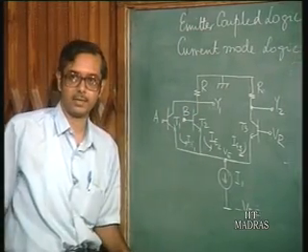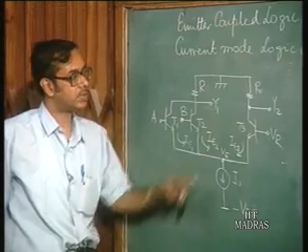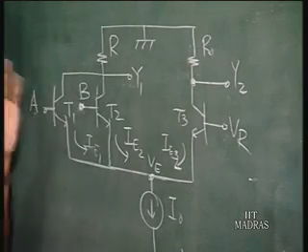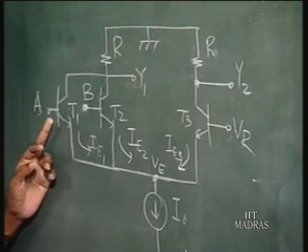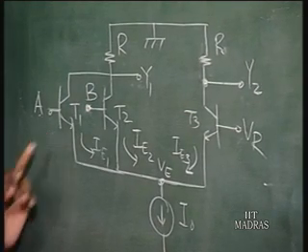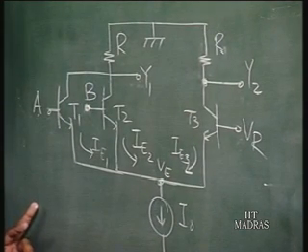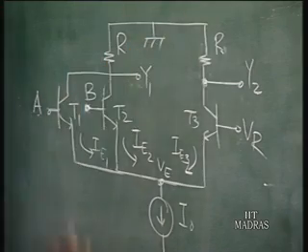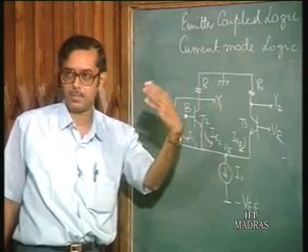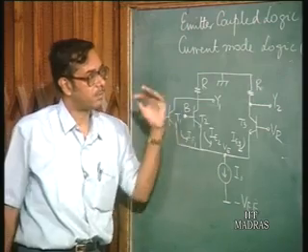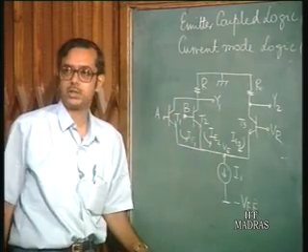Now, if we come back to this circuit again, this is an OR NOR gate. You have both OR and NOR outputs, and this output is to be fed as input to another gate. So there is some problem which we see right away. We expect the input voltage to vary from minus V on to minus twice V on, because that is how we have designed it. Vr is minus 3/2 V on, so V input should be Vr plus or minus half V on. So it should be from minus V on to minus twice V on. But what is the output voltage here?